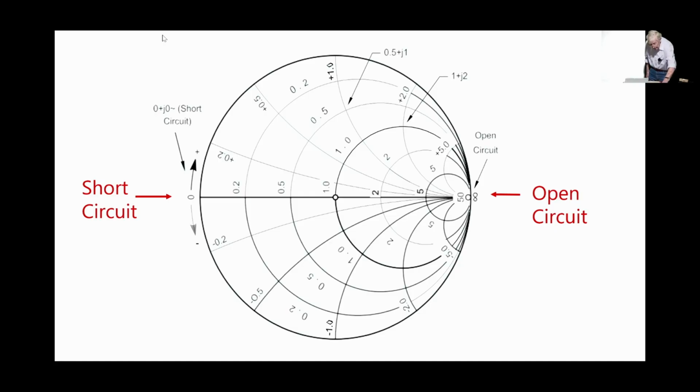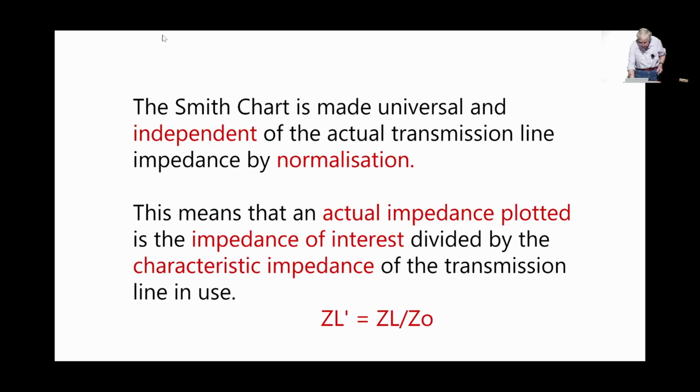And I've got an example here where, just put that in your transmission line and presuming that the length of that is appropriate for your application, you've got yourself a notch filter. It happens that the Q of that's not too good, but not sure why that is, but I did do a sweep of it. I think I've got a graph of it here shortly.